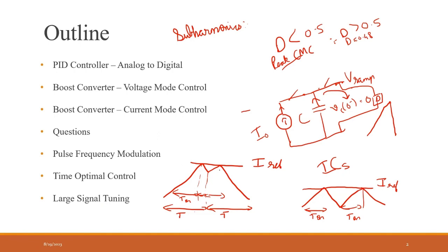So this is a problem with fixed frequency because this time period is fixed. The current is not allowed to fall back. That is the issue with fixed frequency. So to overcome these sort of things known as subharmonics, we use something known as a compensation ramp.